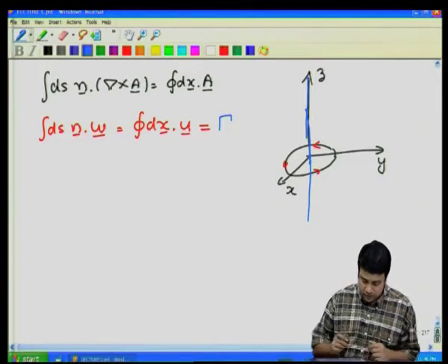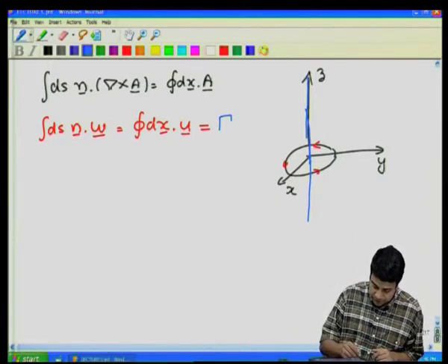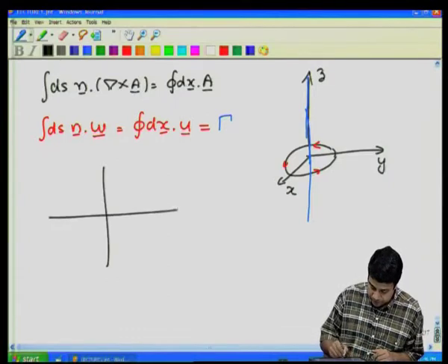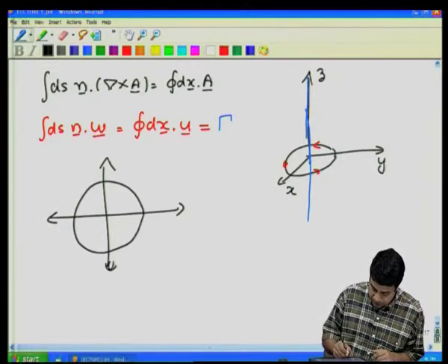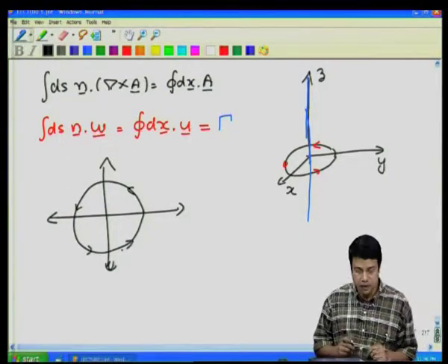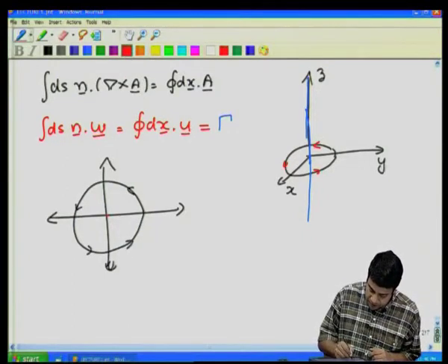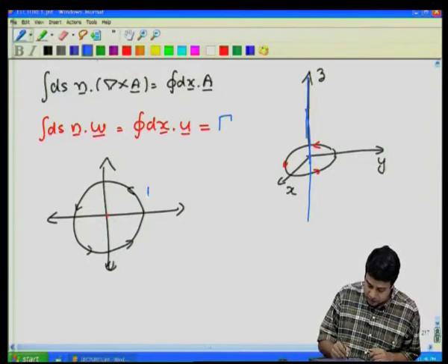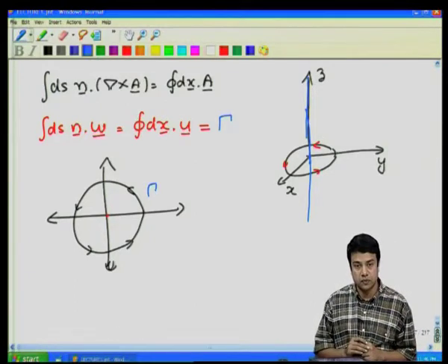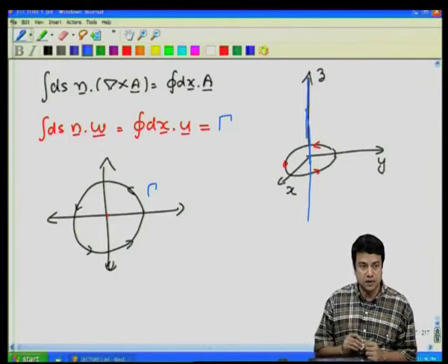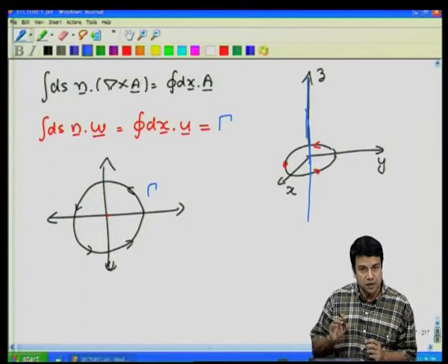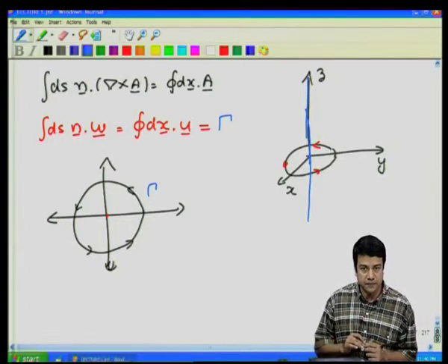So, therefore, what will happen is that if I take a two-dimensional plane, and I go all the way around the origin, since the vorticity is a delta function at the origin, the circulation here around this surface will in general be non-zero, because only at the origin I have a delta function vorticity. Because of that, the circulation is non-zero in any contour that includes the origin.